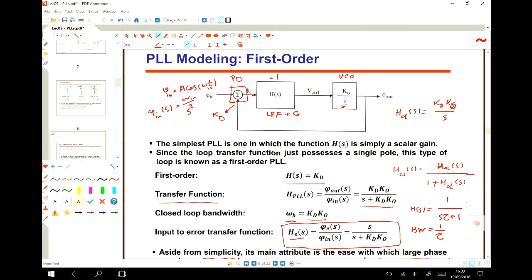But if we write down the function for the VCO, as I already wrote, omega of t equals, assume this is the gain Ko, times the control voltage Vc of t. So this is the equation for a VCO. True? A VCO output, omega or F, no difference, is dependent on the voltage input.